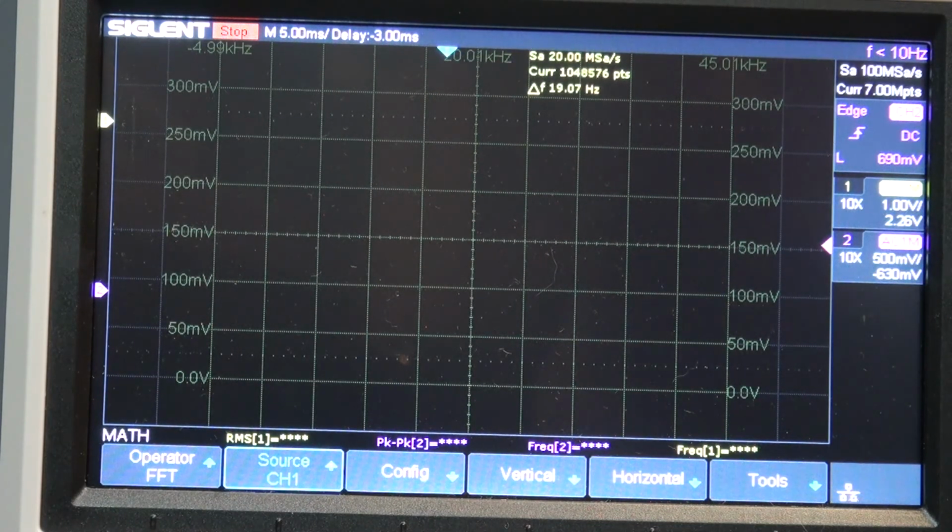So 20 kilohertz local oscillator frequency, that is the upper audible limit of human hearing, and that should shift the audible spectrum and flip it, mirror flip it, invert it into the difference frequencies region of the audible spectrum and create some frequencies that are not flipped. Oh, so two side bands. Okay, let's see what they look like.